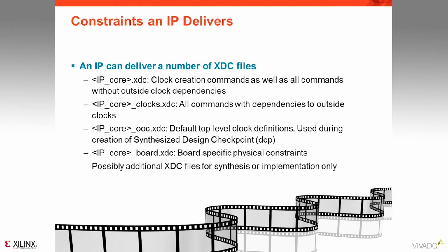The _ooc.xdc file contains default top-level clock definitions for the IP. This file is only used in the creation of the synthesized design checkpoint file if the default flow is used. Since the IP is synthesized out of context of the top level and other IP that would provide the clocks, this file is needed to provide the clock definitions.